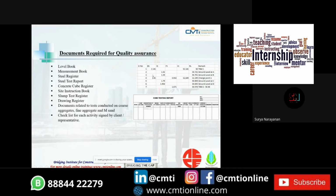This is a level book which gives information like serial number, backsight, intermediate sight, foresights, height of instrument, reduced levels and remarks. This is a concrete cube register where we get information like date of casting, curing days like 7 or 28 days test, date of testing, weight of cube, sizes of cube, etc.